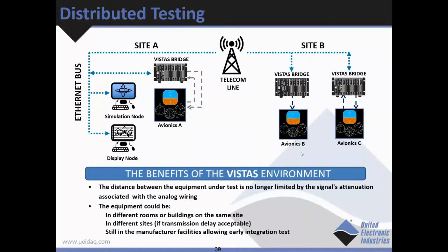Using IP or UDP to connect virtual and real-world hardware accomplishes the system test in an efficient and cost-effective manner. If the hardware is not present, it can be simulated. The simulation can be run remotely with the simulation communicating with the hardware via IP or UDP messages. Real hardware can be switched in at any time.